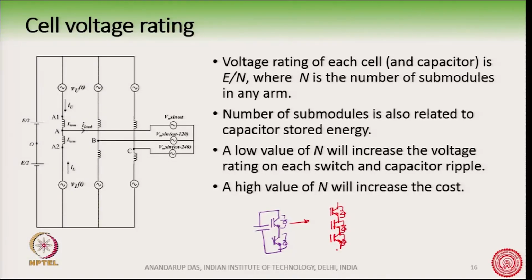Okay. So, some manufacturers have this. This one IGBT is not a single IGBT, but several series connected IGBTs. Now, this cannot be directly said. It needs to be simulated, and we have to find out what the complexity is and what the loss is. Remember, the loss is very important, because we have a large number of series connected devices.